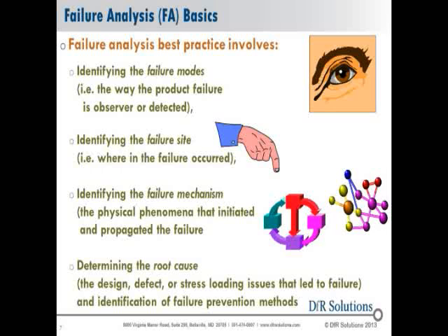Now, in a lot of organizations, the terms failure mode and failure mechanism are used interchangeably. And we don't do that when we are applying a physics of failure approach. We understand that the failure mode is how you observe or detect the problem, and the mechanism is the condition, the chain of events, the deterministic causes that led to the failure to occur. And so we want to have all of this in order to determine the true root cause that led to the failure so we can come up with an effective failure prevention strategy.